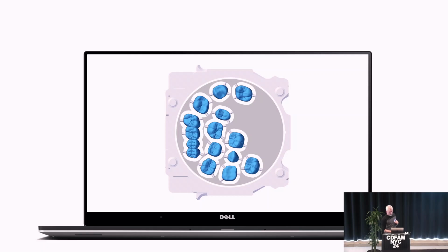We also do this for milling, for example, with crowns that are milled out of a zirconia disc. These crowns are fixtured with small pins. These pins are added automatically, but there are proximal surfaces, where the crown actually touches the teeth on the side. You absolutely don't want pins on these proximal surfaces, because that requires a lot more polishing afterwards to get them removed. A human can look at these proximal surfaces and immediately know where they are. For a model to learn that was non-trivial.